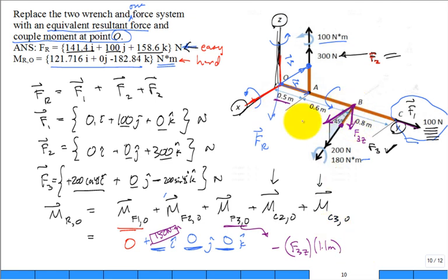How about this F3 in the X? Does it make it want to rotate around the X? No. Does it rotate around the Y? No. Only around the Z. So this was contributed around the I, and this will contribute around the K, right? And it'll be the magnitude F3 in the X. What's its perpendicular distance?